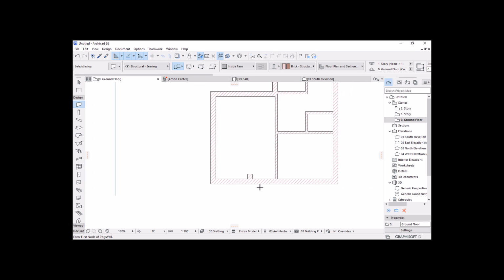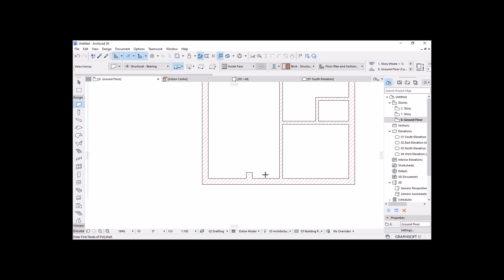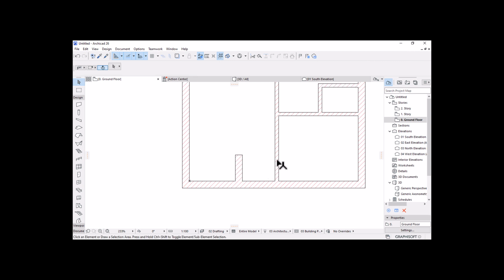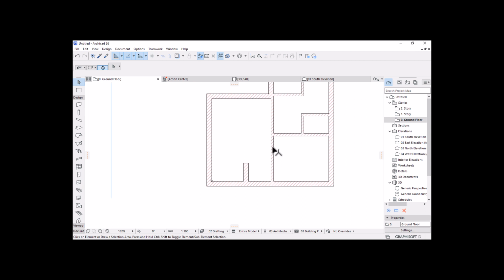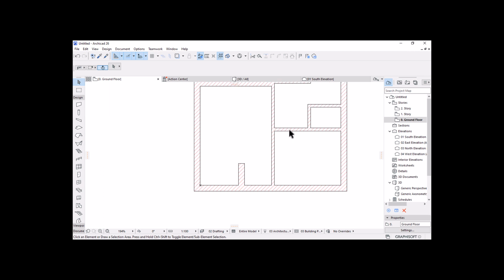It's fine. What I need to do is that this wall, I need to extend it. Maybe let's make it 1.1. Right, the wall is 1.1, and then we have to have the same wall on this side instead of having the wall all the way 115 to here. So to achieve this, we need to create an opening here, right? So to achieve that, I would split this wall into two.